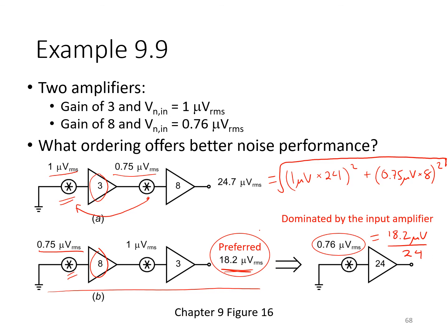And so it illustrates why we often use a so-called low noise amplifier to amplify small amplitude signals as the first stage. These stages are designed to have as low an input referred noise as possible, so they don't corrupt the small amplitude input signal, and should have at least a modest gain, but they may not require a particularly large gain.